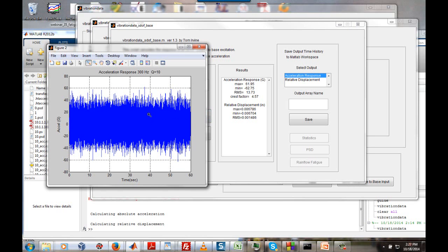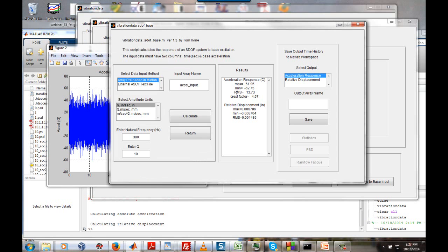That means that the standard deviation and the RMS value are the same. I'll show you the formula shortly, but we've covered it before. Sometimes we get a little bit lazy and use 1 sigma standard deviation and RMS values interchangeably. But anyway, if we take the peak absolute value and divide by the RMS, it comes out to be a crest factor of 4.57.